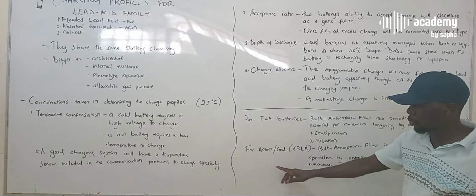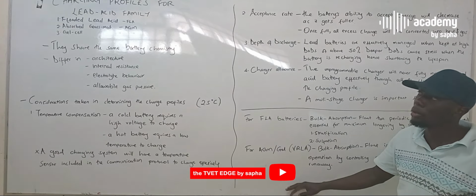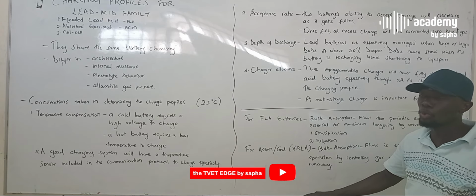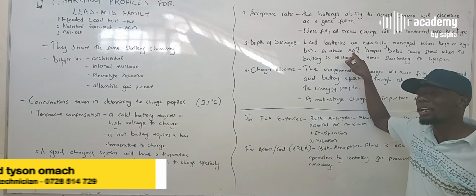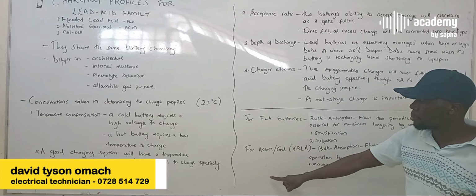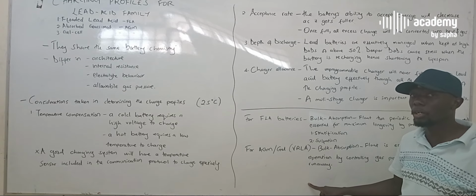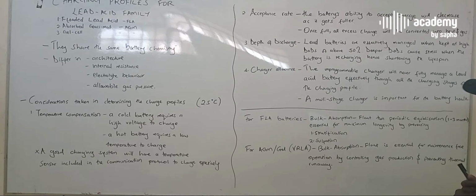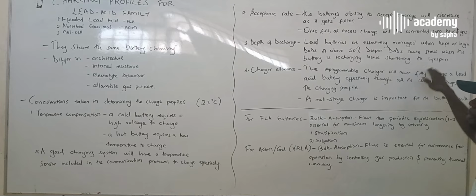So, for example, if you size your system and the client is going to use a lead acid battery, the FLA or the gel battery, ensure that you size your system to never be depleted beyond 50%. When the battery is at 100% in the evening, size your system in such a way that by the time tomorrow morning comes, the battery will not have gone below 50%. That's what this means, because deeper depth of discharge causes stress on lead acid cells, and when internal stress is constant, it shortens the lifespan of the battery pack.